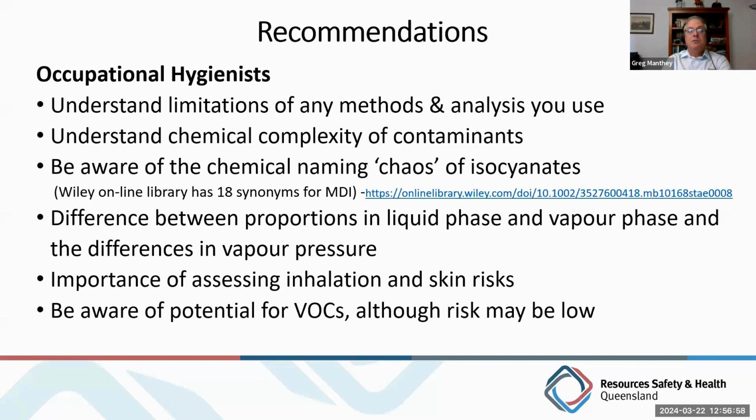Consider the difference between proportions in a liquid phase and a vapor phase, and what the differences in vapor pressure might mean in terms of converting a risk of exposure from a liquid to a risk from a vapor. And it's important to assess, particularly with isocyanates, the potential for inhalation and skin risk, and be aware of those VOCs.